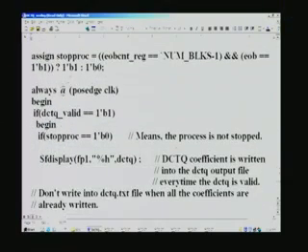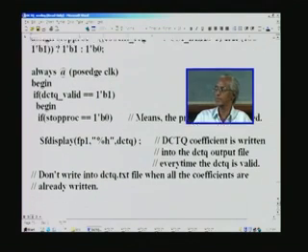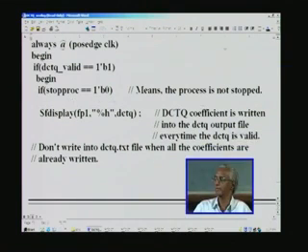So, next thing is we need a signal called stop process in order to stop the entire thing after one frame is already completed, DCTQ value computed and stored in dctq.txt file, and this expression does that precisely. The running counter is examined for number of blocks, and also we see that end of block is also 1, only then we take this action, and if that is not met, that means DCTQ processing is still going on. Only then we write into the output file, which is dctq.txt, and if it is 1, we will not write here. So, that means stop process will go right at the end of all the blocks being processed.